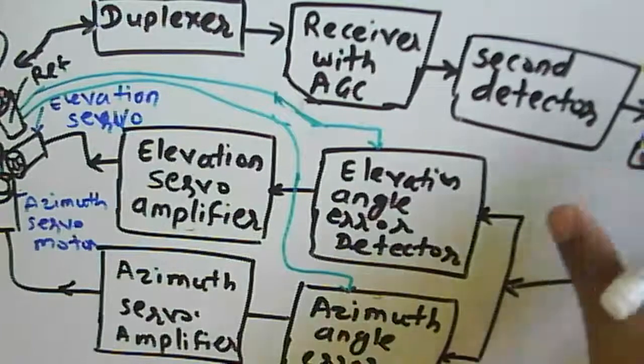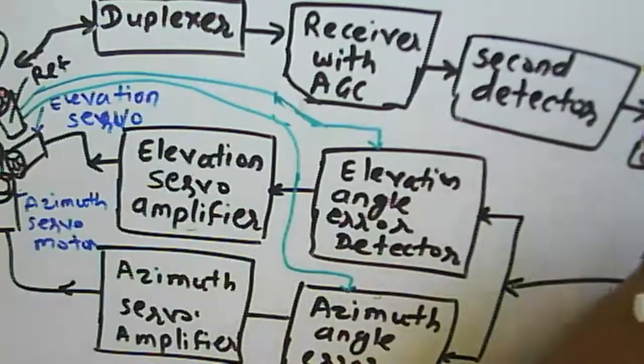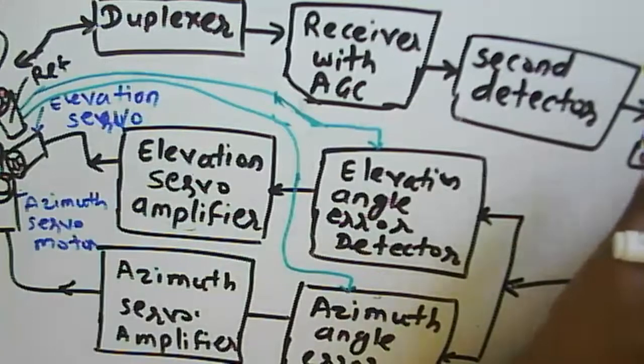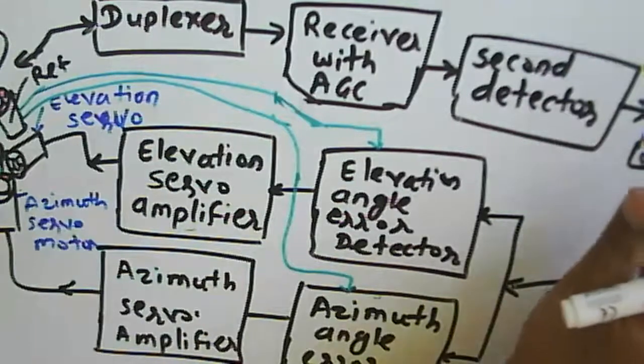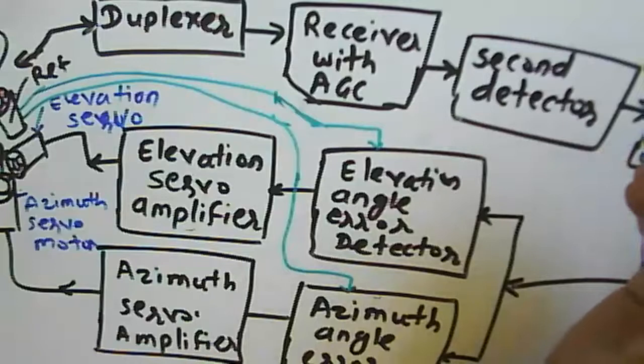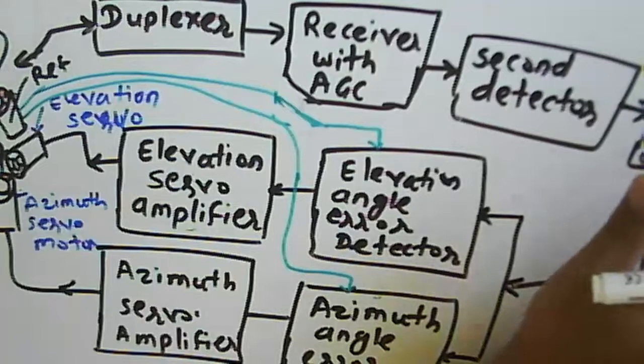In a simple manner, range gating is nothing but a low pass filter as well as a sample and hold circuit. It is just like stretching the given pulse in a particular direction. That's why, in other words, range gating is called a boxcar generator.